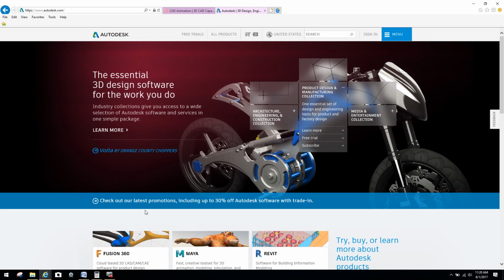I'm not going into full detail, but you are going to require at least 5 motors, at the very least 5 motors, 5 drivers or a driver for every motor, pending, of course, you don't have a slaved axis and whatnot. I'm not getting into all that. I'm just telling you the base you would need. And then, of course, power supplies to support all that, your enclosure, VFD, spindle.